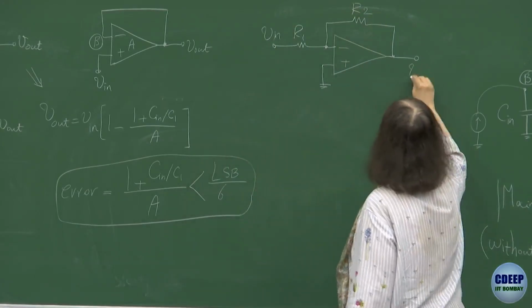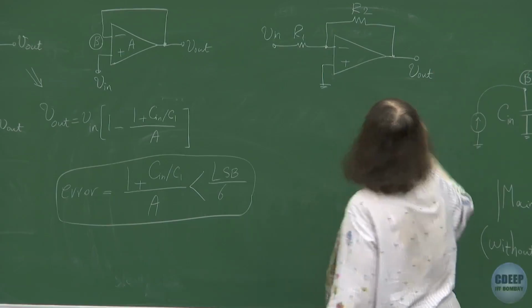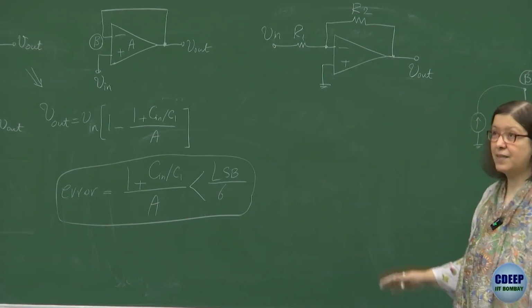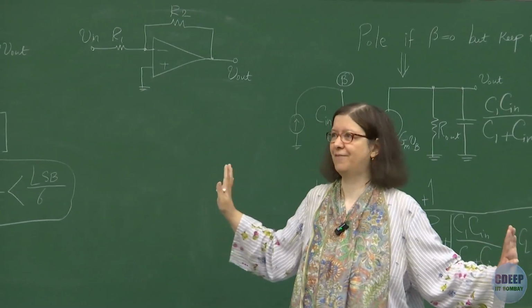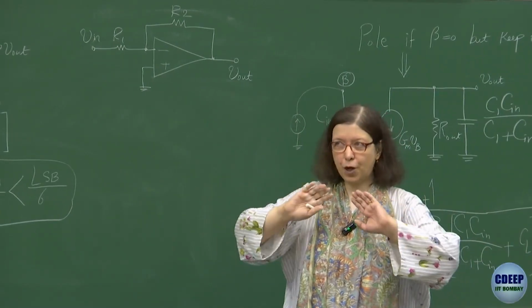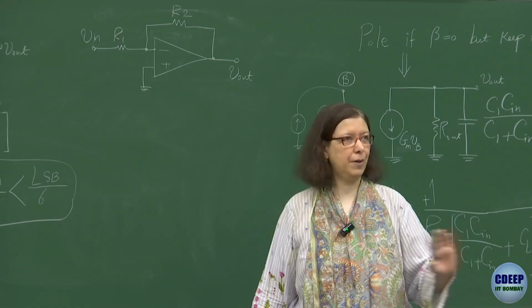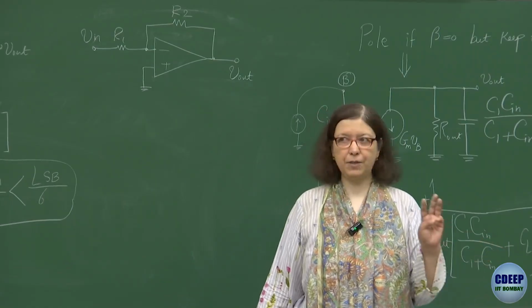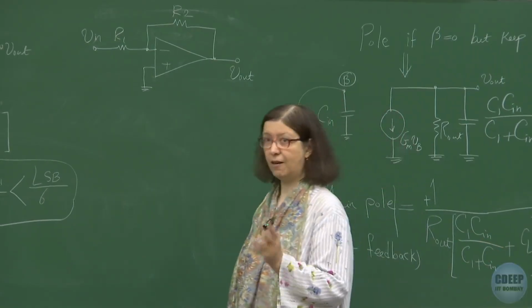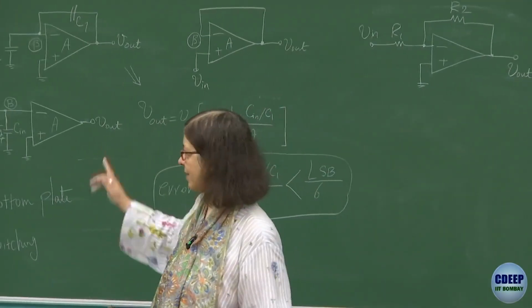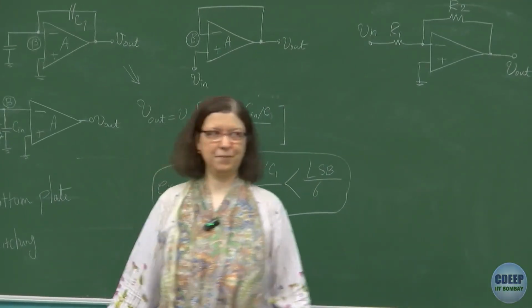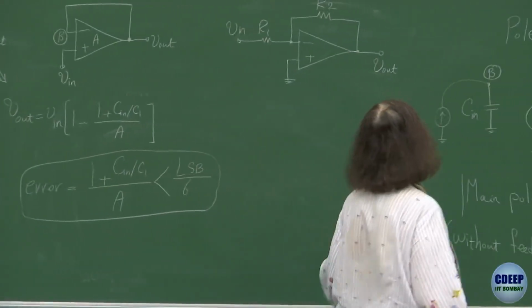If I want to make a counterpart of this in discrete time, one advantage of discrete time is there is no resistor. Therefore, one source of problems, including variations, a large area, and power dissipation, goes away. That's why discrete time circuits are so popular. They bring too many things together.